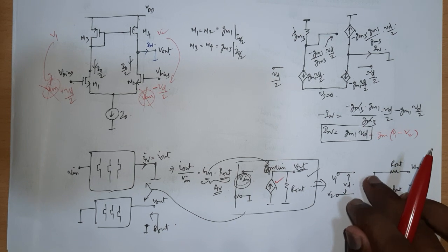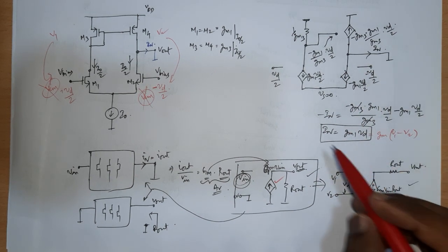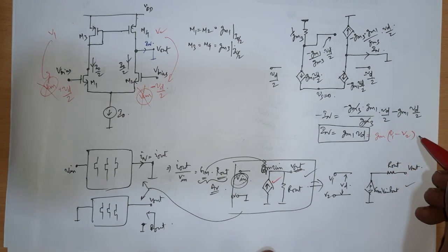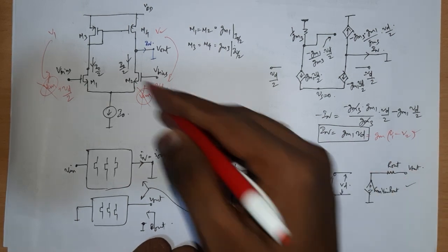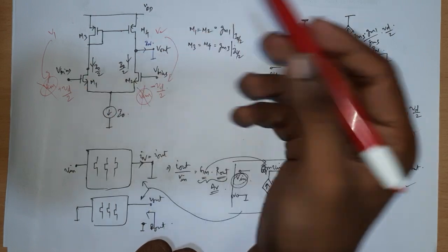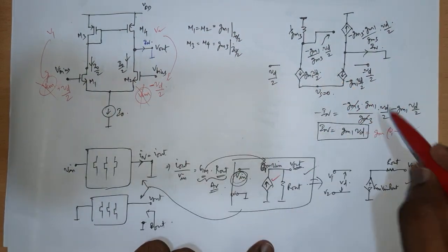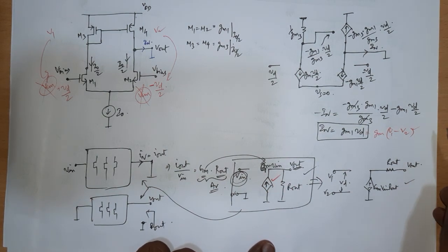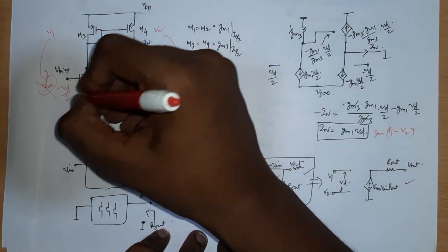So as far as the differential signals are concerned, this is the incremental picture, okay. Incremental picture will have this current source of value GM1 times V1 minus V2, okay, or GM1 times VD, okay. This is what we wanted and we got it, okay. Now for common mode the circuit is not responsive, but then we'll see what happens. But for differential mode, as far as differential inputs are concerned, you can replace it with the current source of value GM1 times V1 minus V2,